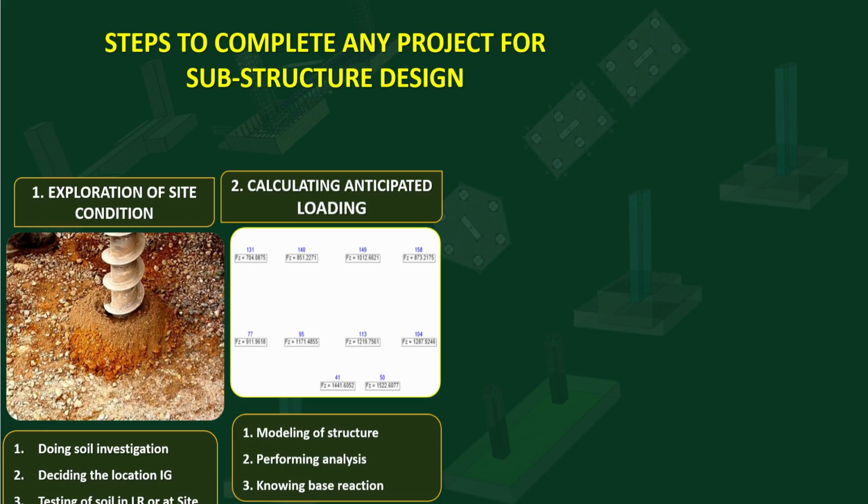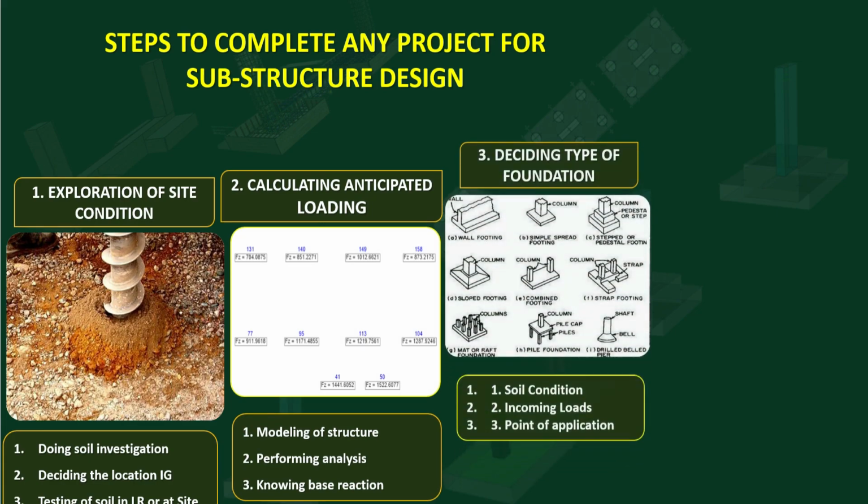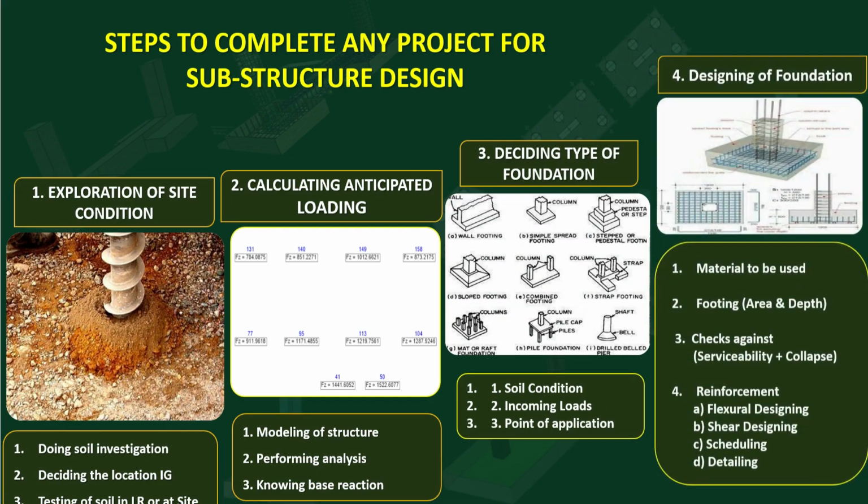So before having the loading, to have the reaction, we need to create the model, perform analysis, and know the base reaction, then you can proceed. And thereafter we will decide what type of foundation will be suitable for our proposed structure. And thereafter we will design the foundation. We will design it for flexure, shear, scheduling, detailing, everything we are trying to cover for our proposed structure.